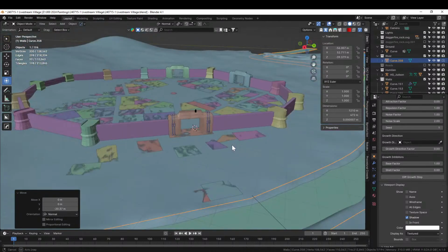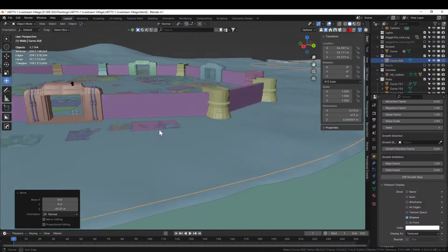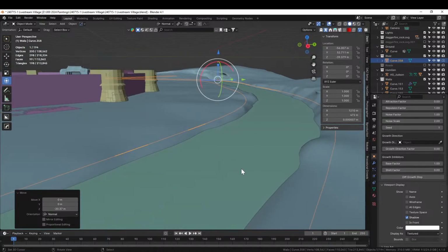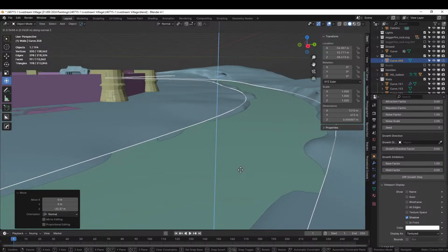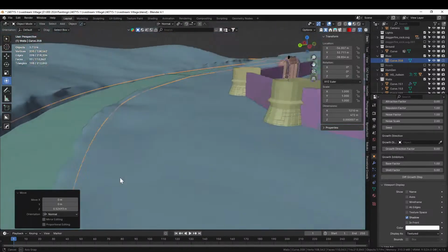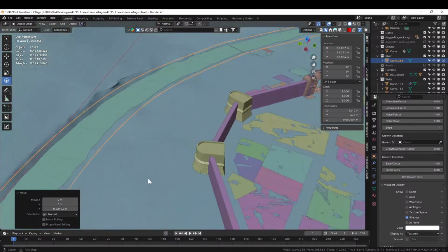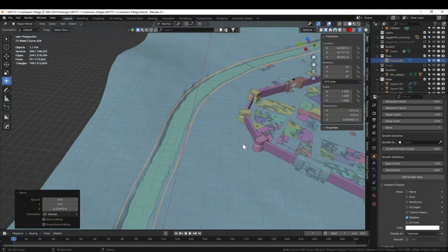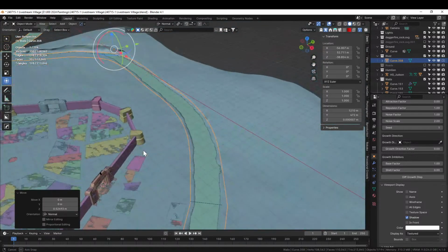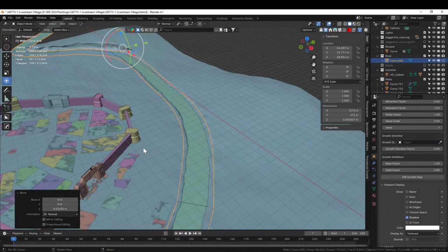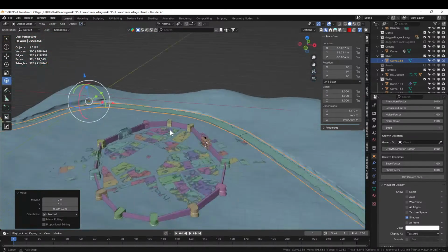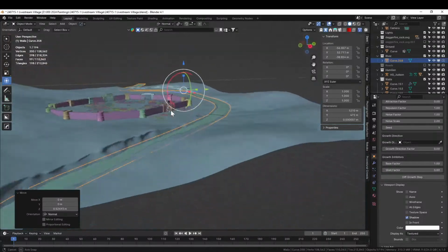If it was flipped backwards, you would notice it and it would look ugly. Like that's a legitimate reason. Now let's keep it down to there. Yeah, that's a good place for water. I don't know if that's a good answer or not, but that is a legitimate use case why you wouldn't want to do it. It also just handles weird when you try to inset later or select linked faces and all that kind of stuff. So it just becomes a pain in your ass.